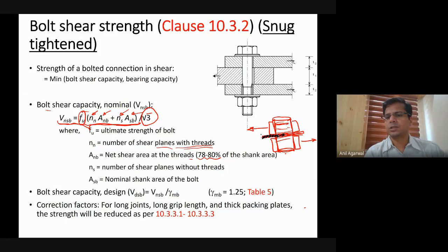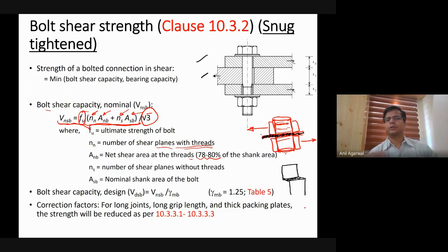Now, if you imagine the shear deformation of this bolt, it will be deforming like this in a single shear problem. The problem here is double shear, by the way. I don't want to draw the entire thing. That's why I'm showing it here like this. Okay, so in this particular case, even if this particular plane where the shear deformation is taking place is undergoing yielding, the yield deformation will not be large enough, because not the entire length is yielding, only a very small length is yielding.